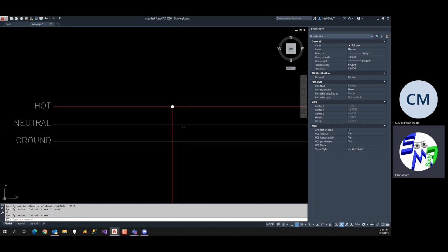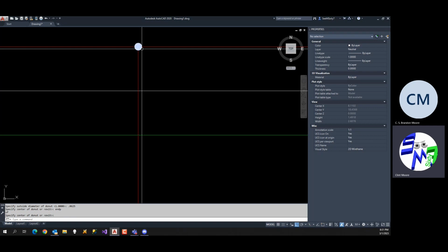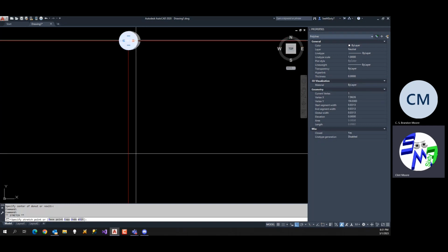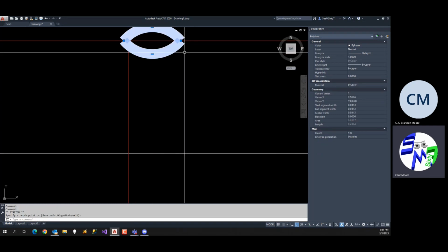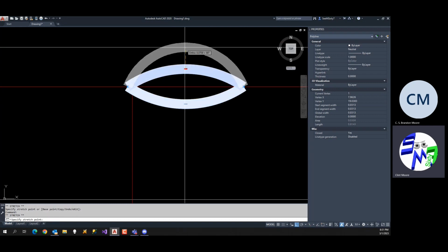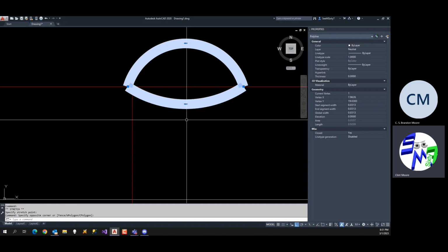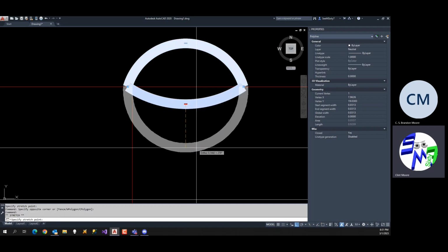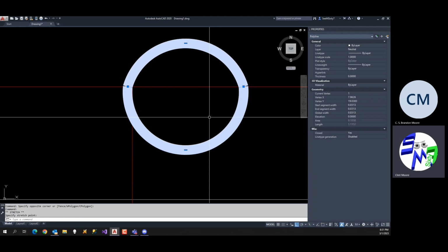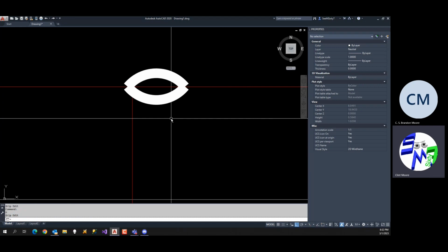Okay. Hit enter. And now you see my solid little dot there. If I want that to be a little bit bigger, I have to actually do this a little bit differently. Because this, if you notice, starts getting kind of quirky. The donut command essentially creates a polyline. Okay. It's just a shortcut for creating a polyline that fits a very specific purpose. So that's why when I start grabbing at the grips, it gets pretty funky. So I'm going to hit undo, undo, undo, undo, undo.